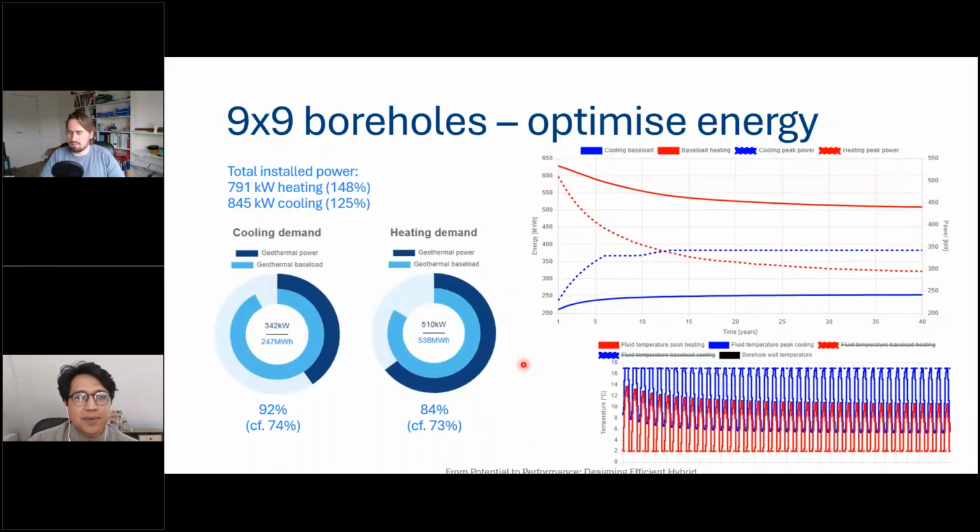Okay, there's another fairly basic question here. Can this tool be used for medium to deep geothermal systems, up to say 1,000-meter boreholes? In the end, it can, because we are able to take into account different ground layers as well. The thing is that it's based on something called g-functions, which assumes that the ground is homogeneous. So if the temperature gradient is not that constant, or you have quite a lot of change in thermal conductivity, the accuracy of the model becomes less.